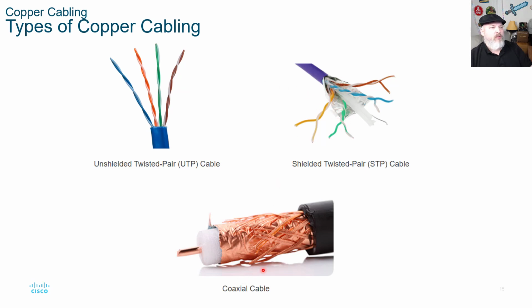And then here's this coax cable down here. If you've ever worked with cabling, video cabling, you've seen coax cable. If you've ever put cable TV into your house, that's coax, RG6. It goes by RG6 in a lot of cases. There are some other forms of it, but the most common type is RG6. It has a common inner line, then plastic sheathing, then some copper metal around it, basically a mesh that cuts down on any interference, and then another plastic sheathing out here.